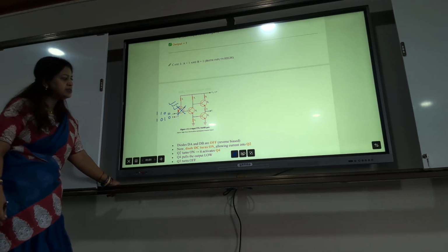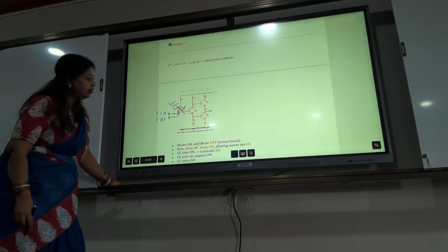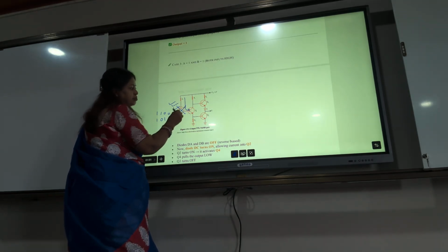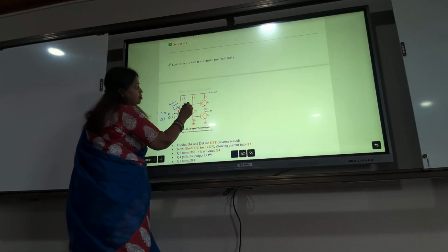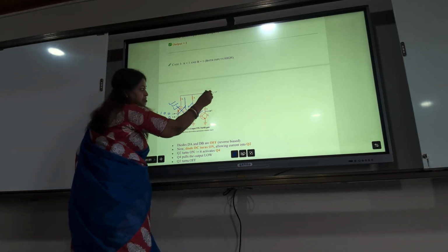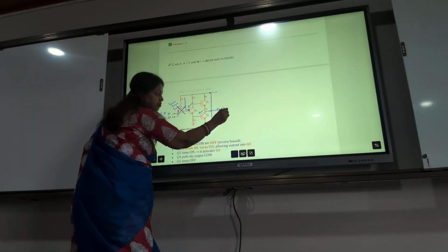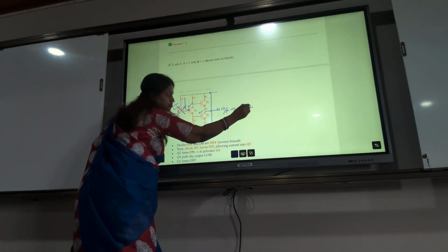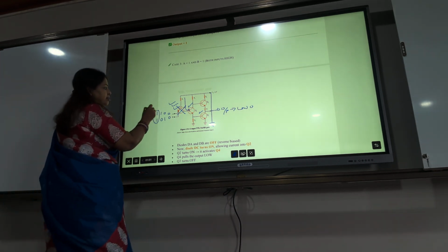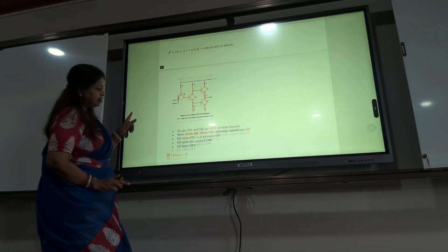So now what happens? Diode DC turns on, allowing current to flow to this side. So this will be on. This will be on. So what happens? Short circuit into ground and now it is moving. So only for the 1, 1 condition, the output is going to be low. So this acts as a NAND gate.